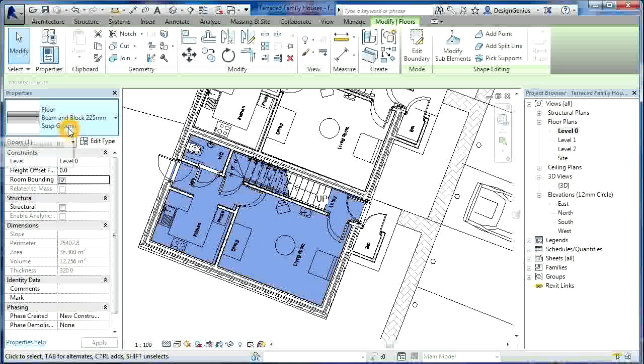First of all, you would have to look at the floor composition, and adjust or change, as we have discussed in previous tutorials, which is really to look at the architectural element itself and use edit type to modify it to what you are looking for.